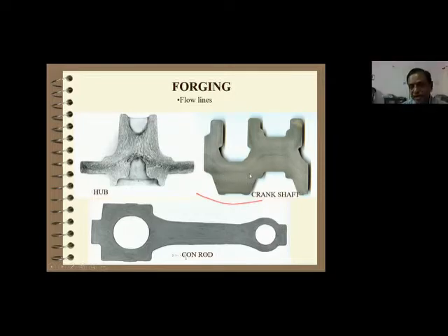And normally when machining takes place, it should not cut over here, because if the grains are cut at a certain angle over here, then that area becomes weak, where during service the chances of failure occur. So the designer has to design the die very properly so that the material flow is safe inside the die cavity, and there is no material flowing outside the die cavity.